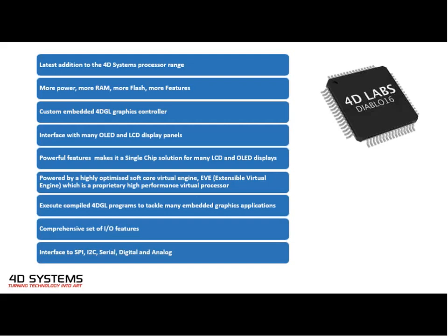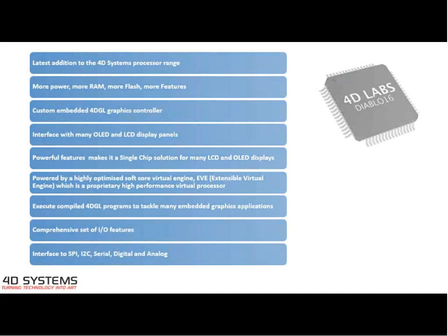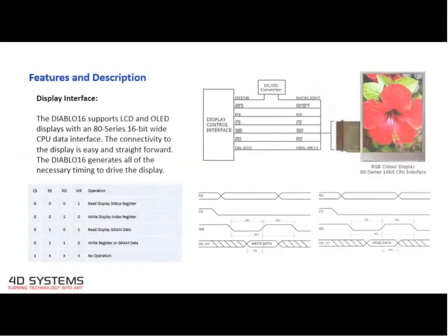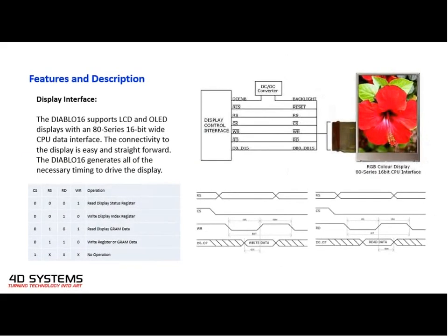So let's look at the interfaces and the features. The display interface. The Diablo16 supports LCD and OLED displays with an 8080 series 16-bit wide CPU data interface. So everything that has something to do with controlling the LCD, like read, write, reset, chip select, it's all there. Here it's the write cycle, and here's the read cycle.